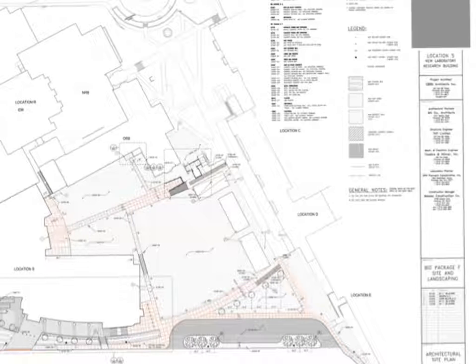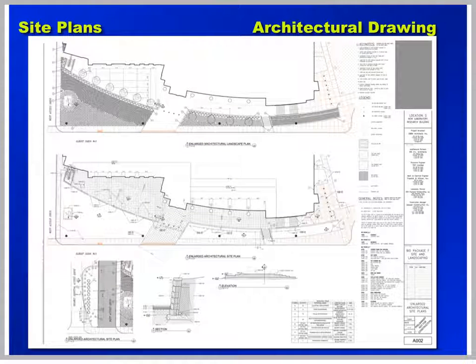What I want to show you is we have some poche over here and some legend for what the poche means that is identified on the project. Like for instance this darker gray area, some sidewalks that you have down along this area. That's very useful in identifying different types of materials on the job without having to write the material name down again and again. Found on this site plan is a blow-up from the previous site plan showing much more detail.